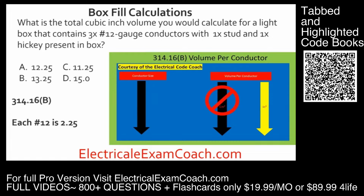Now let's count our conductors. We know that we have the 3 number 12s originally, but now we have to deal with the studs and the hickeys. Our code states that each stud and each hickey counts as 1 each, based off the largest conductor that's in the box. In this case, we only have number 12s, so they're going to be grouped with the 12s. So that lets us know that we have a total of 5 number 12s. That's what I meant by we're converting everything back to conductors, and then we can do our multiplication. We take those 5 number 12s, multiply by the cubic inch volume for 12, and we end up with 11.25 cubic inches, and we would select C.